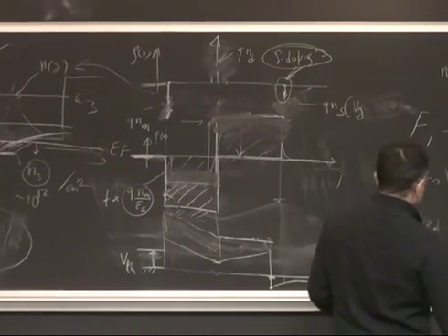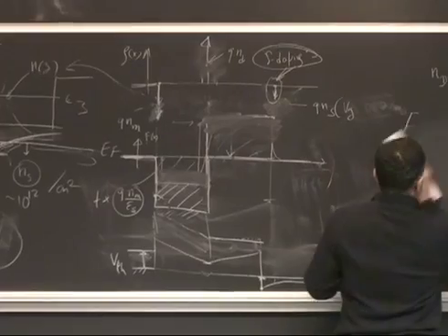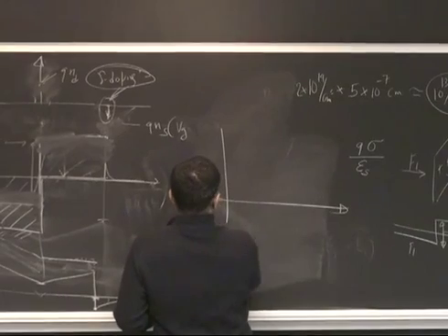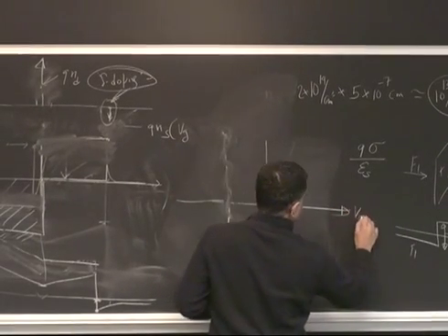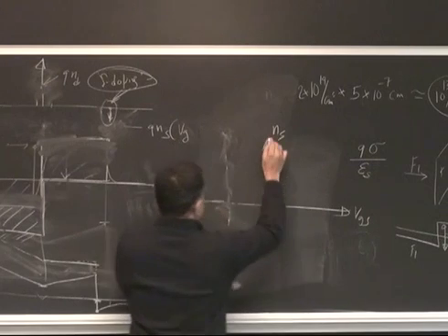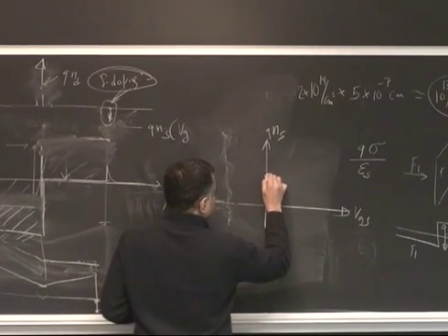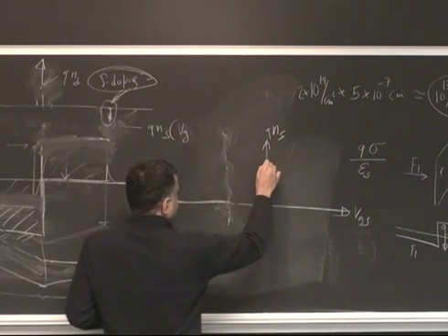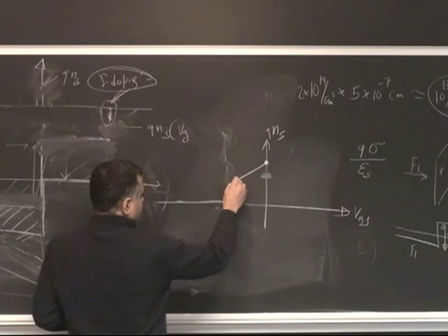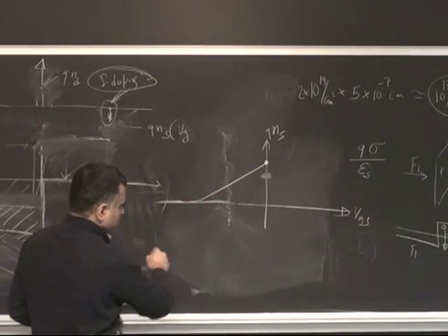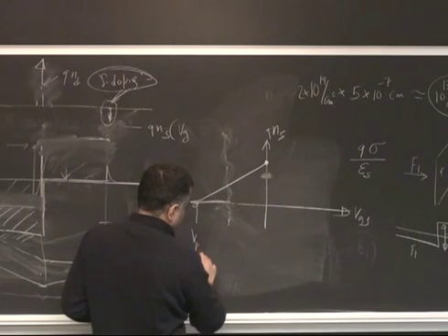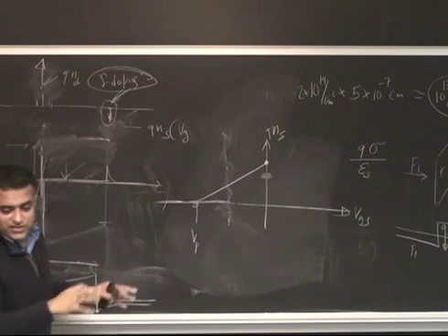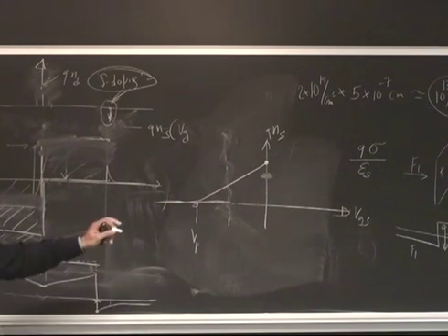So if you now measure your electron gas density in the channel as a function of the gate voltage, what you would get is, let's see, VGS versus carrier density in the channel, or q times ns. At 0 gate voltage, we just saw 2E12 charge for the example we're looking at. And what I'm trying to say now is, as you apply negative voltage, it's going to go down, and merge with 0. And that's what we're calling the pinch-off voltage or the threshold voltage. It's a negative voltage here because you started with some electrons in the channel already. Right? Is that okay? Yeah.